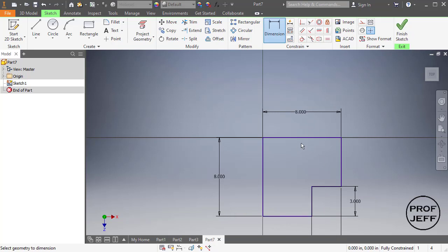Now inside of the shape, we had a circle. So I'm going to put that circle in there. Now you can see I've got a bunch of snaps that are coming on here. Now I know that that is in the middle of this side, and it lines up with this front edge. So actually I've got these snaps. I could put this in here and it would completely constrain it to that point just the way I want it.